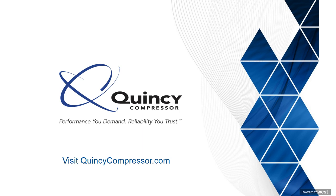The biggest change will be the publishing of isentropic efficiency, and the new DOE standard should be called out. It might be in the form of 10 CFR, or it might call out the DOE as a reference. Best thing to do is to ask if this is to ISO 1217 or if it's in compliance with the DOE regulation. The presence of pressure ratio and isentropic efficiency is the first clue that you're likely looking at official compliant data with the Department of Energy regulation.